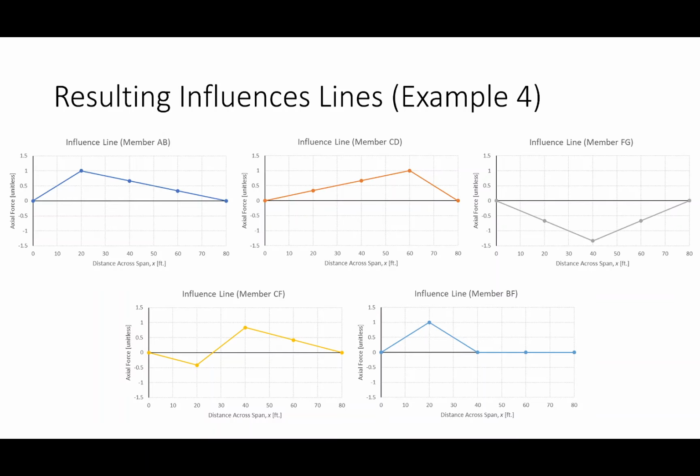This is just 0, 1, 2/3, 1/3, 0. That's just me plotting that. The whole thing's positive, right? It's all positive. Why? Because it's a member on the bottom of the truss. When you move a load across the structure, let's assume it's a beam. A truss is just a beam with really big holes in it, right? So imagine a truss goes like that, the bottom's in tension. As the load moves across the structure, there's no way this member isn't in tension, right?